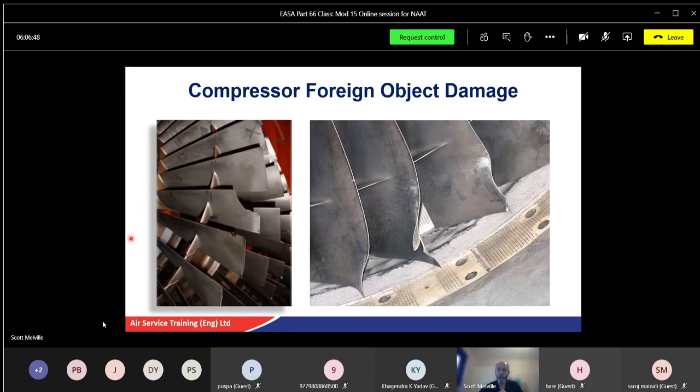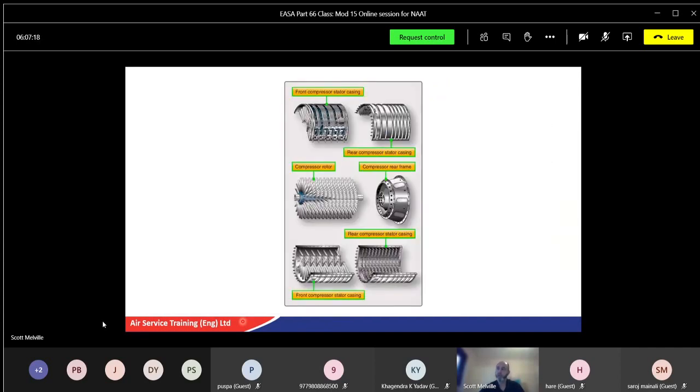Anything else on that? Interference between tips and shrouds casing can cause damage caused by surge. Again, a surge can cause a blade to come forward, and indeed you might get shingling, where the snubbers might go over the top of another snubber. Okay, so like this one here might go over the top of that. Very rare, but it does happen. Look for bending, cracks, and so on. Again, all the information is laid down for each specific blade, but definitely in your blade areas, you're only allowed to fix certain parts or blend certain parts.